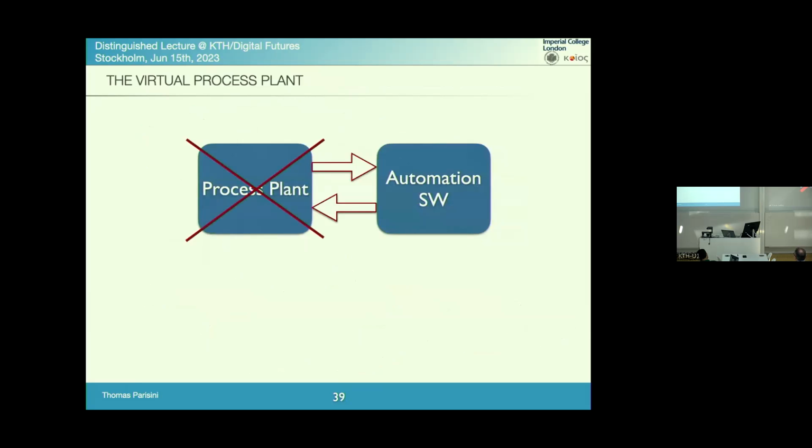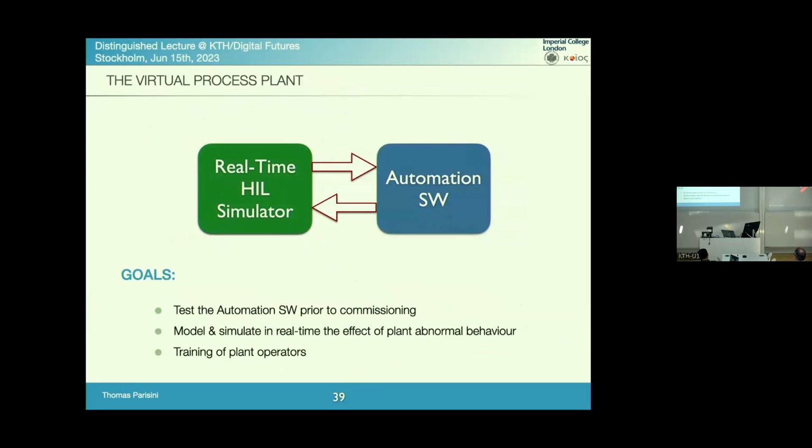I already explained that. I would like only to say, and that might be interesting for any of you that is not interested at all in fault diagnosis, but might be interested in what the digital twin helps with in industry: not only to diagnose faults, as I'm going to show, but also because before plugging your automation system into the plant, which they call commissioning the automation system, if you have a digital twin, of course, you can do virtual commissioning.